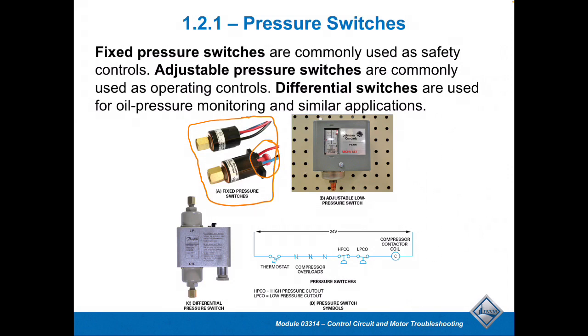That would be an example of, let's say, a high pressure control or a low pressure control that would be a loss of charge type control. If the system were to fail, you'd have to push that little red button into the control to reset the safety, and then it would allow it to function again. That's one example. This particular control here is an adjustable control, and there's usually going to be some sort of a setting up and down on the top of this one that allows the adjustability, whether it's higher or lower, and a person has to look at those.